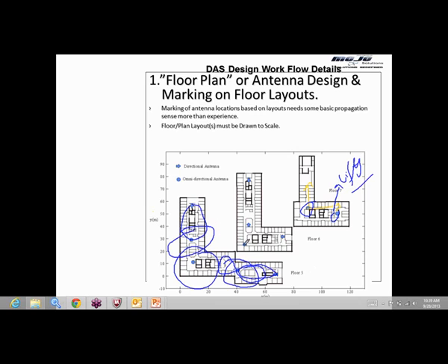So the reason over here, maybe there is an elevator and they want coverage in the elevator, so they install one antenna over here, one antenna over here, and this is the elevator area, so they are covering that from both directions. This is a lobby hall with the elevators, to make sure all the lobby is covered very well. Similarly, they are pointing the direction over here to cover all this area because there may be some stairways or something which needs to be covered. Okay, so there is a thought process behind why and how these antennas are placed initially.